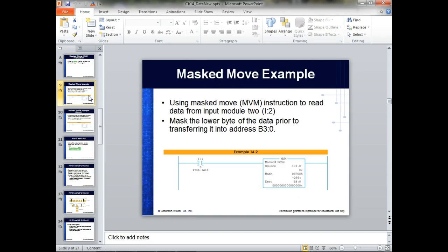Index addressing, everybody okay with that? That's the way you specify it, but it allows us to automatically go through addresses without us trying to specify all of them, right? It's used by your bit shift left and bit shift right. It allows you to use shifts of greater than 16 bits. We can shift left greater than 16. We can shift right greater than 16. We showed y'all that. It allows us a temporary storage location so we can save stuff on the stack.